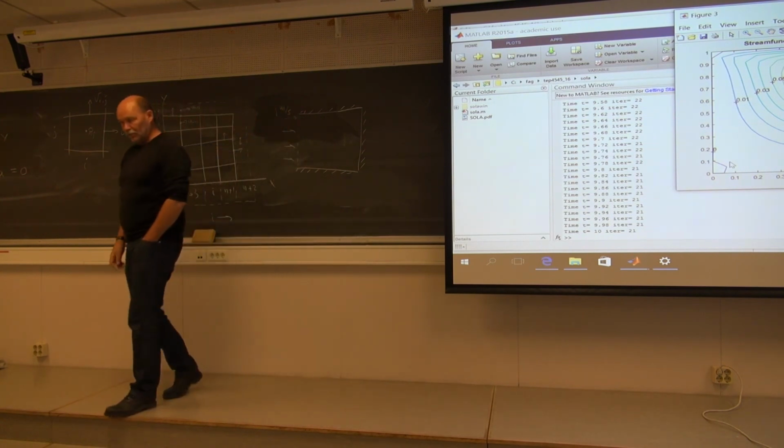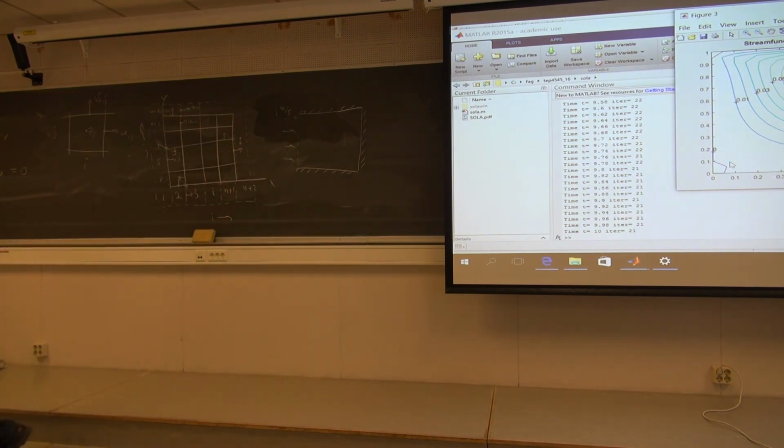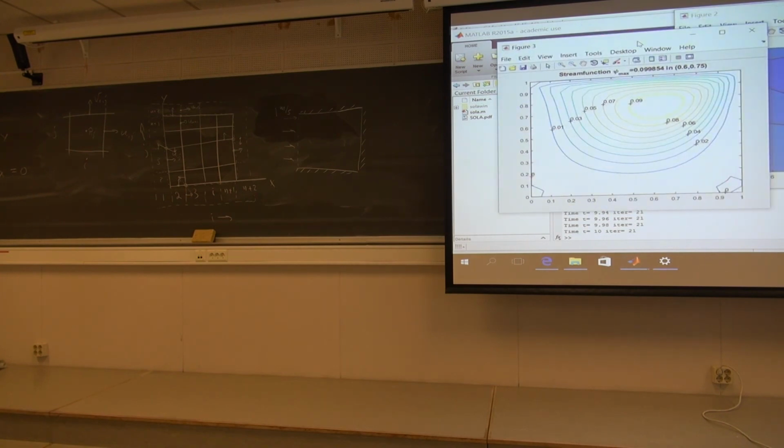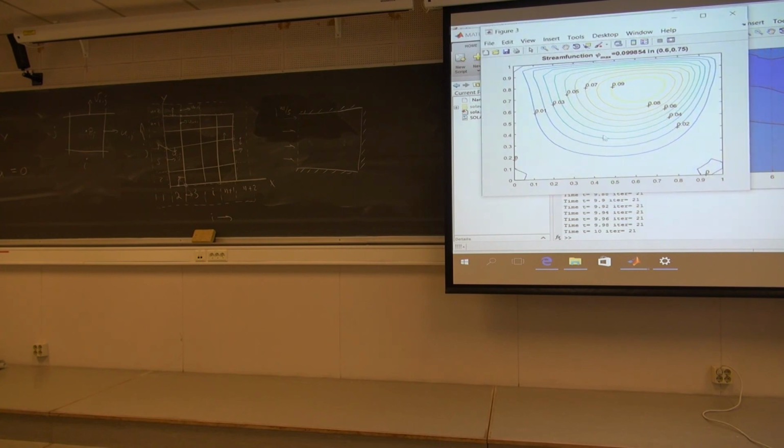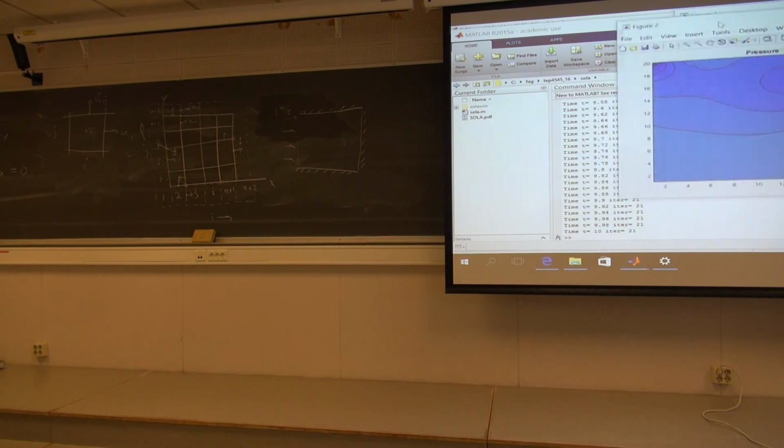Then what's going to happen? I have an inlet. I force in 1 meters per second. But now I forget the outlet. So hopefully the code will explode. Let's see if it does. Now this was the square cavity test case. No problem here.